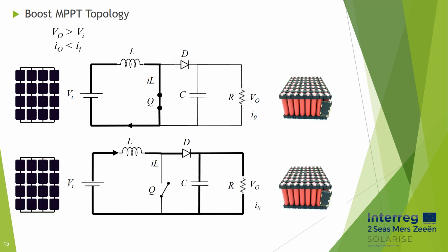When the switch is in the off state, the increase in impedance reduces the current. To maintain the current through the load, the magnetic field is used. The polarity will be reversed, which results in two sources being in series. This causes a higher voltage to charge the capacitor through the diode. In boost-type MPPTs, the battery side, or the output voltage, is higher than the solar array side.